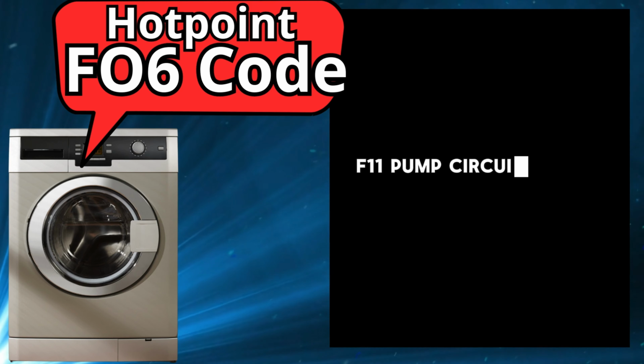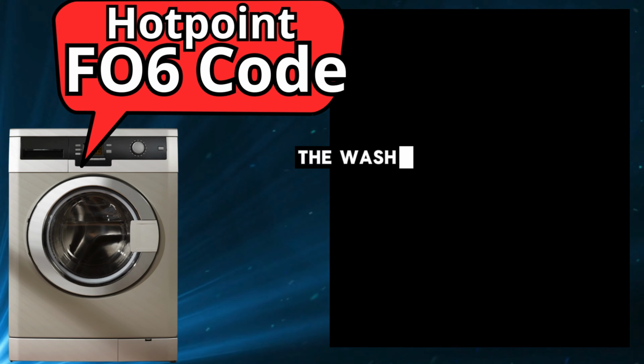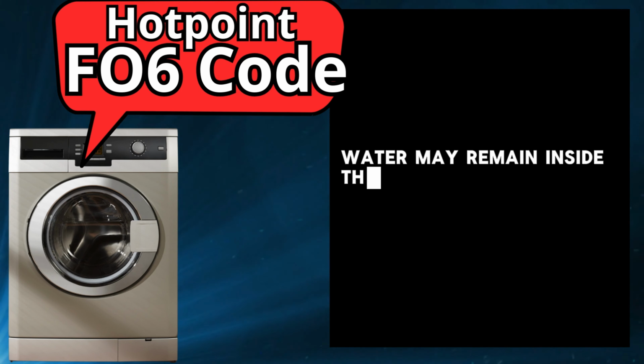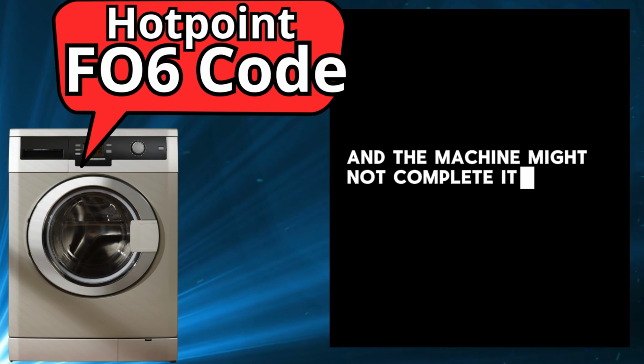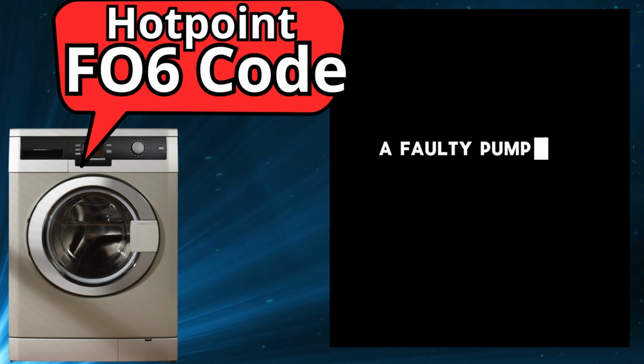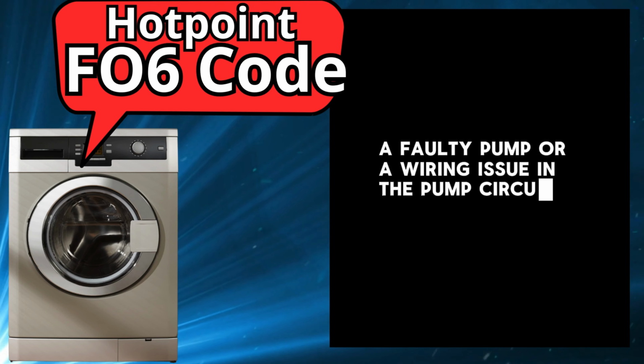F11, pump circuit fault. This error means that the washing machine is unable to drain water properly. Water may remain inside the drum, and the machine might not complete its cycle. Possible causes include a blocked drain hose, a faulty pump, or a wiring issue in the pump circuit.